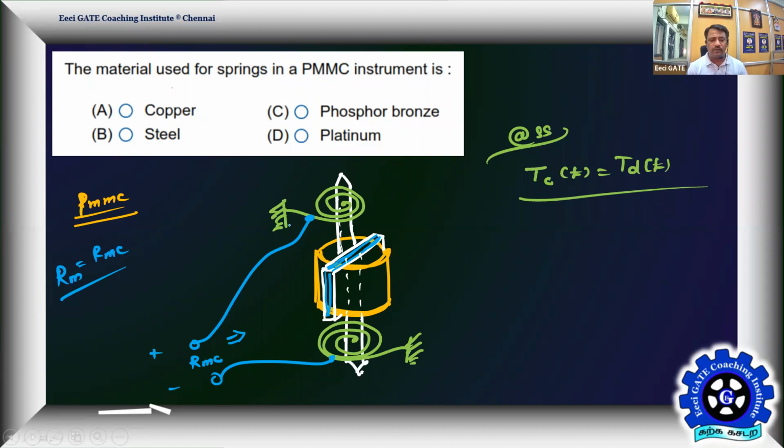Now the current which we are about to pass to the moving coil passes through this. We connect a wire here, and then a wire here, like this, so that the moving assembly won't get disturbed. So we pass the current to the moving coil only through the two springs. This one has a stiffness K by 2, and this one also has the stiffness K by 2. The net spring stiffness we take as K. They have the responsibility of offering such a stiffness.